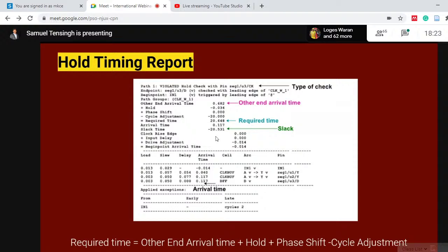In each step of your physical design, in placement, clock step, post clock, route, post route, you will have timing reports being generated by Innovus. So you can intermittently check all these timing reports to clear out the violations, and the later sign off for the design is usually done using PrimeTime, which is from Synopsys. So the timing engines are different between PrimeTime and Cadence. So the STA engineer will give feedback to the design engineer on where to fix all the violations in the timing failing parts.